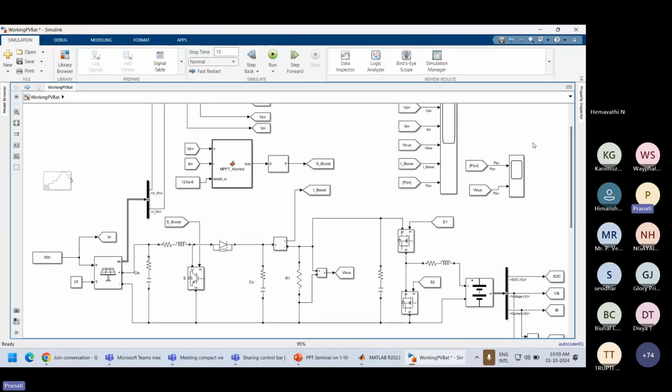It doesn't follow immediately. That is why the controller needs to be designed properly and accurately. Then only it will follow the immediate change. You can see this when I show you with this signal generator: with the immediate change of the irradiances, our controller accurately follows because the controller parameters KP and KI are designed properly.